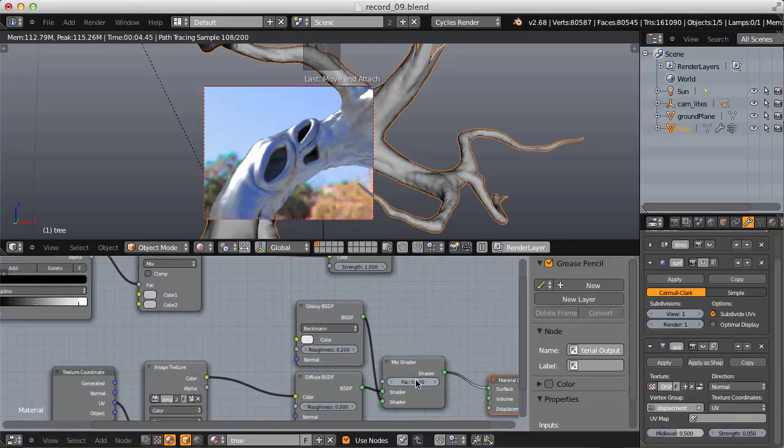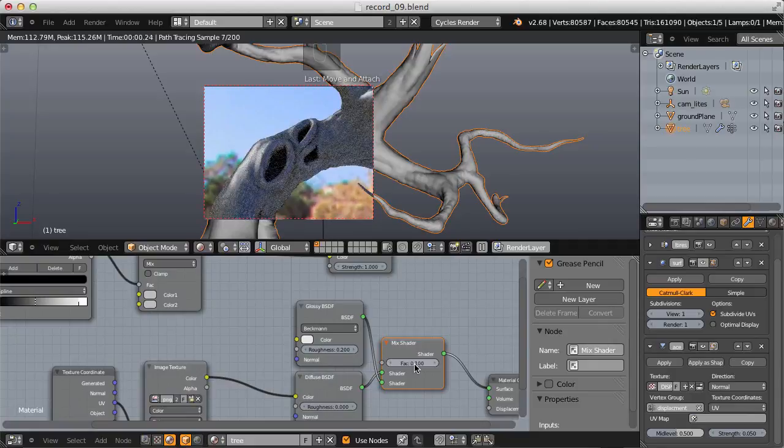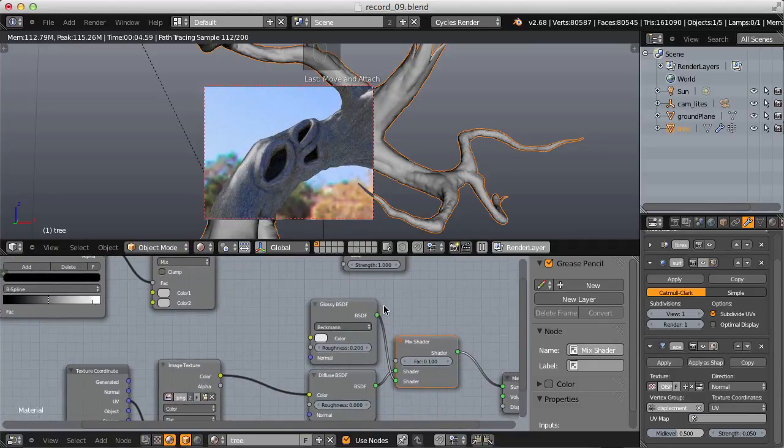So a value of 0.5 is way too much. Let's dial that down to 0.1. Yeah, I think that's okay. How about a roughness value of 0.3? Yeah, I think that's appropriate. A tree really isn't shiny. It just has a slight reflectivity, especially when we come around the sides because of Fresnel.